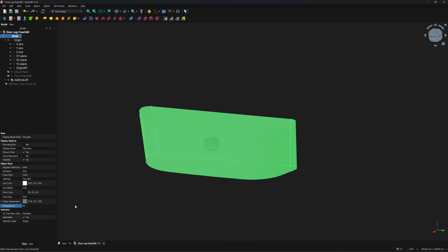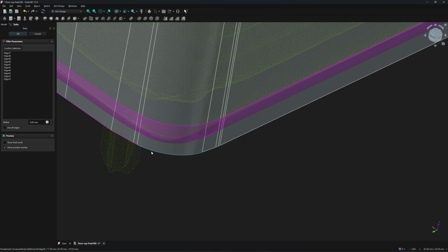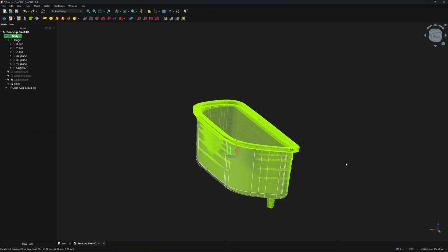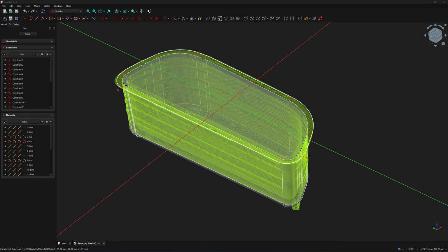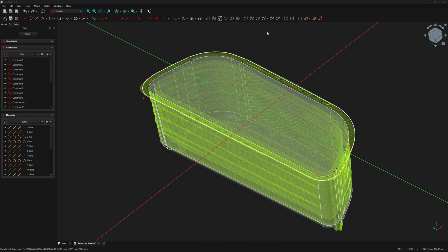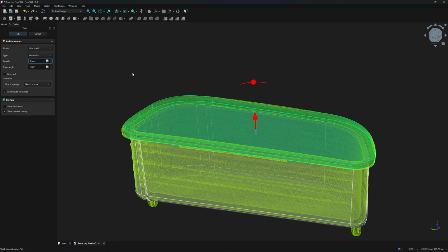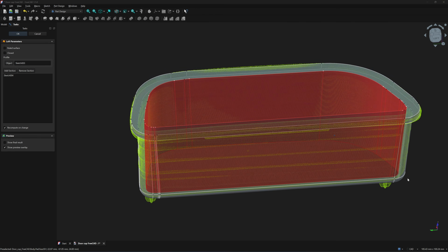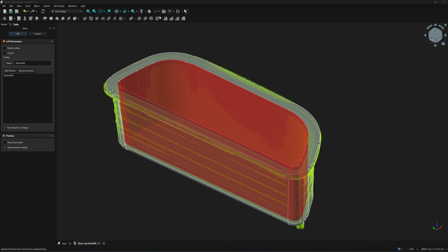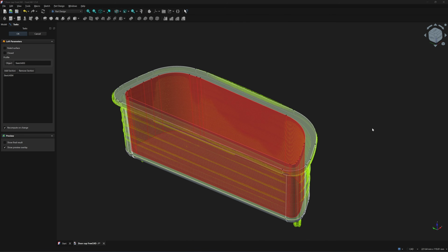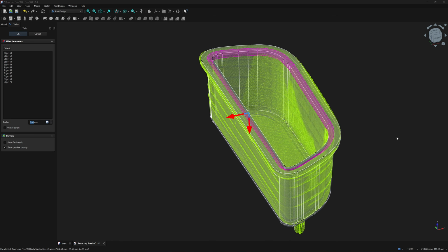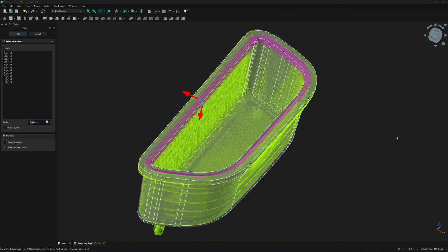During recording, FreeCAD crashed, which also affects the screen capture software. From this point onward, there won't be live footage of the modeling process. FreeCAD failed to run the thicken command, so I created 2 additional sketch profiles and used loft cutting to hollow out the solid. This command also caused FreeCAD to crash. But at least you can use loft cut to create the wall. And the corner fillet is still functional without any issue.